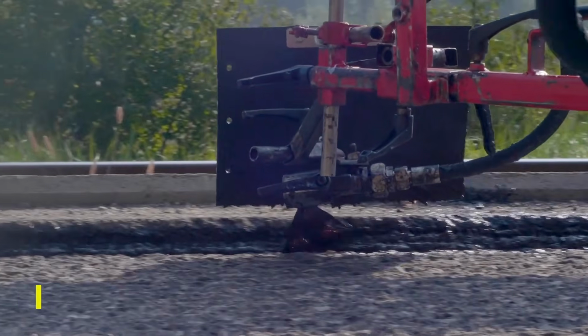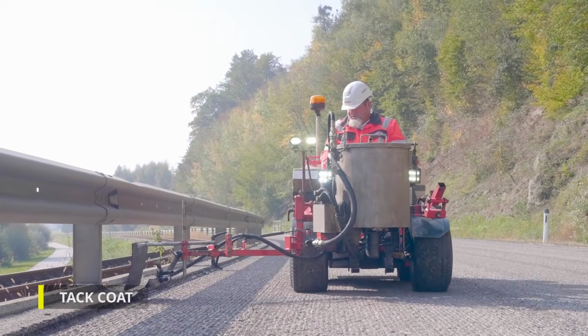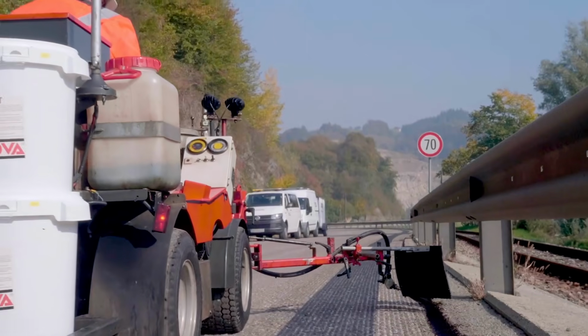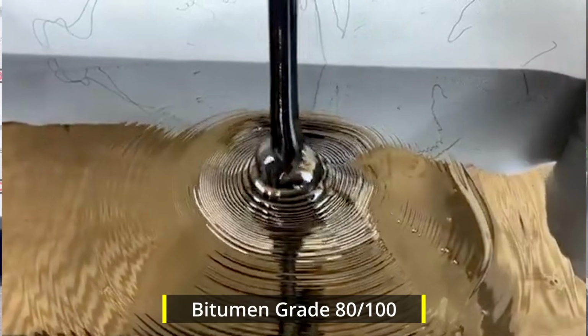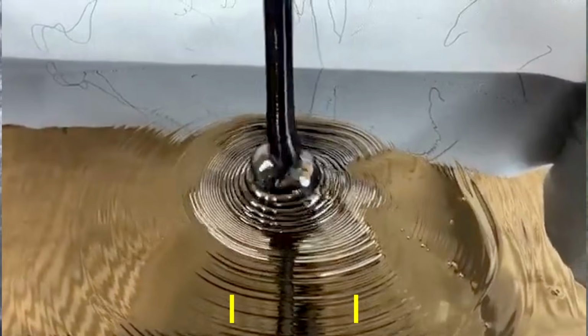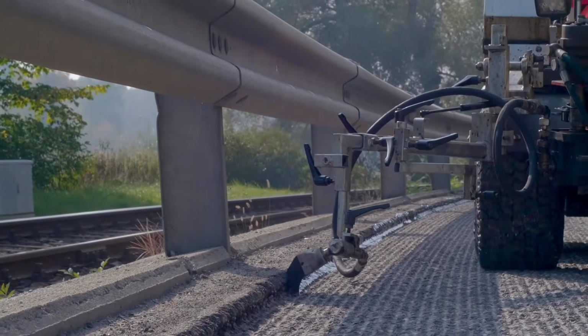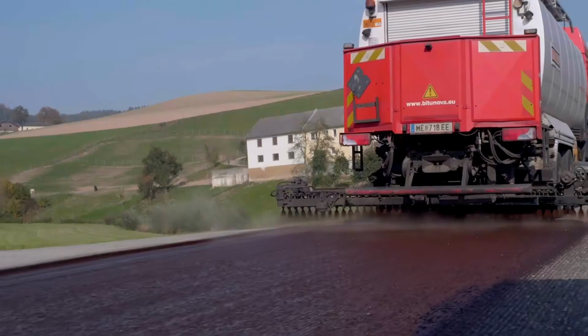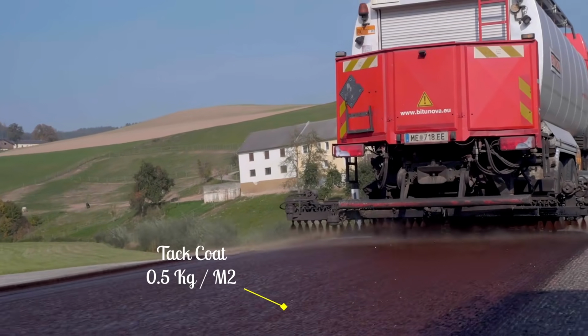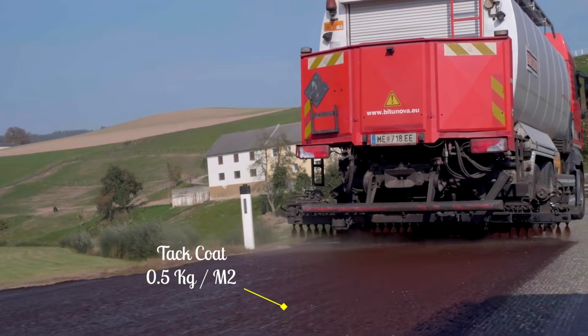The tack coat. The tack coat is the binding layer between two bituminous surfaces. Bitumen of grade 80 to 100 is used for the tack coat. It shall be heated to around 150 to 160 degrees Celsius and uniformly sprayed at about 0.5 kilograms per square meter using a mechanical sprayer. It is generally applied just before laying the next layer.